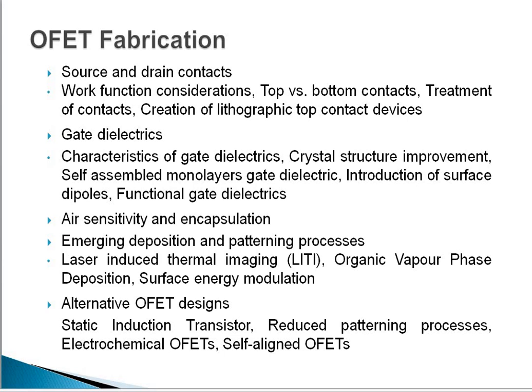The next factor is the gate dielectric. I will cover the following topics: characteristics of the gate dielectric, crystal structure improvement, self-assembled monolayer gate dielectric, introduction of surface dipole, and functional gate dielectric. Next is air sensitivity and encapsulation. Next are emerging deposition and patterning processes, in which I will cover laser-induced thermal imaging, organic vapor phase deposition, and surface energy modulation. Alternative OFET designs are available: static induction transistor, reduced patterning processes, electrochemical OFETs, and self-aligned organic field effect transistors.